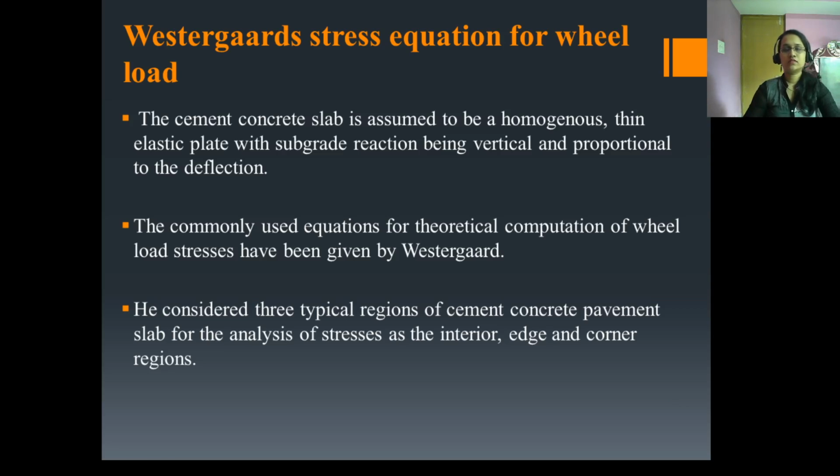Now Westergaard's stress equation for the wheel load. The cement concrete slab is assumed to be a homogeneous thin elastic plate, with subgrade reaction being vertical and proportional to the deflection. So here Westergaard considered three typical regions of the cement concrete pavement slab for the analysis of the stresses. These regions are the interior, edge and the corner regions.